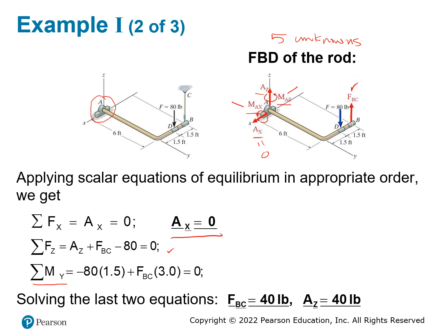So when you sum the moment in the y direction, which rotates about like this, right? It will be caused by this force or this force. And if you select the reference point at this point, then this force is not going to give you any y moment as well because it goes through the y axis directly. It intersects that y axis. So none of these forces will create any rotation around the y axis. So you only consider AD and FBC.